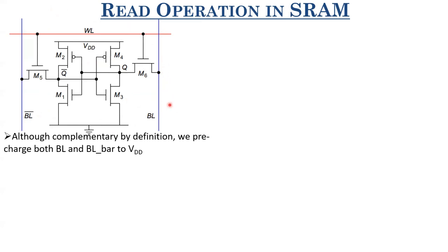So this bitline will actually have a capacitance CBL, which is typically in picofarad range. And what would be the components? The components would be first the CGD of all these SRAM cells, CGD of all these access transistors connected to this BL. Its interconnect capacitance, that is parasitic. Input capacitance of that sense amplifier, as well as the capacitance offered by this pre-charge circuit at the top and sense amplifier at the bottom. So those capacitances form CBL, and similarly you'll have CBL bar because all of them are connected between bitline and bitline bar. So whatever is CBL bar will also be the same.